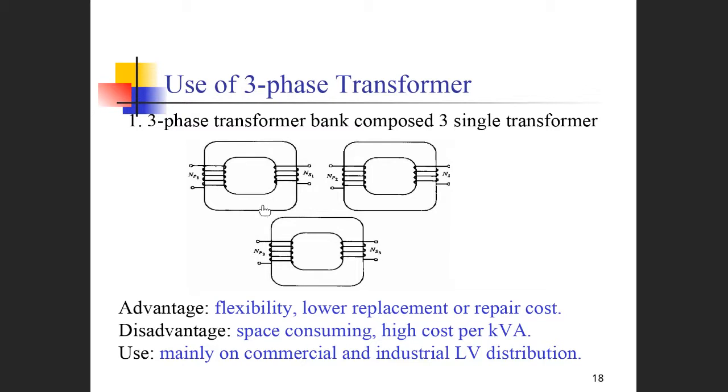This is the flexibility. Also, if the transformer has some problems, with one phase we just need to replace one single transformer, rather than open the whole transformer. That's the meaning of the lower replacement or repair cost.